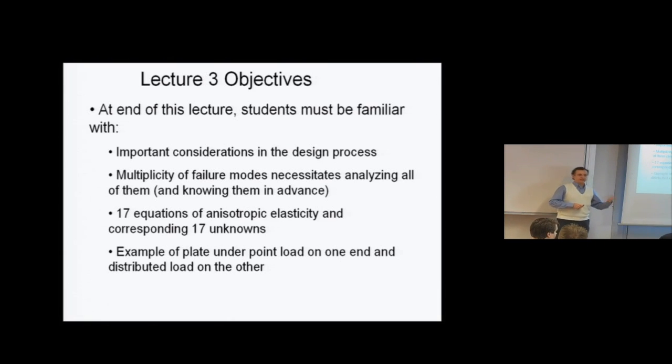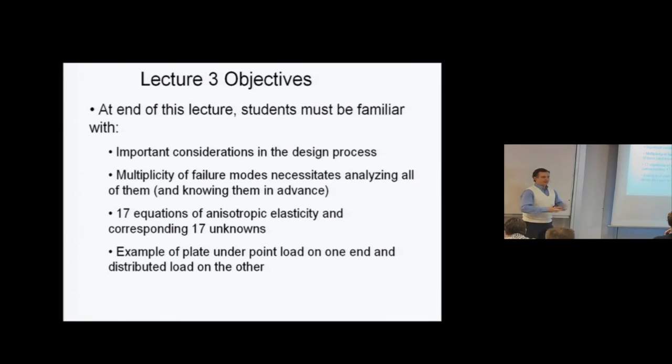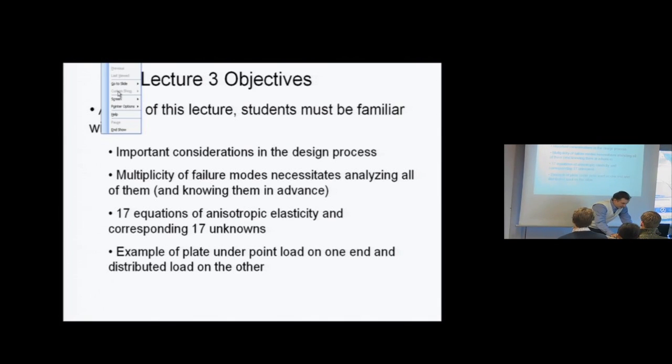Let me say up front that it becomes crucial to know the failure mode for which you are analyzing. If you don't know it, then you might miss it. This finite element code or whatever you are using is tailored to the construction that you made up, and it may not be able to tell you it's going to fail at this specific failure mode, and it might miss it. I'll show you examples throughout the course. Then we'll do the full-blown 17 equations in 17 unknowns for anisotropic elasticity, and we'll even start solving those for some relatively simple cases where we can solve them in closed form. So, having said all this as background,